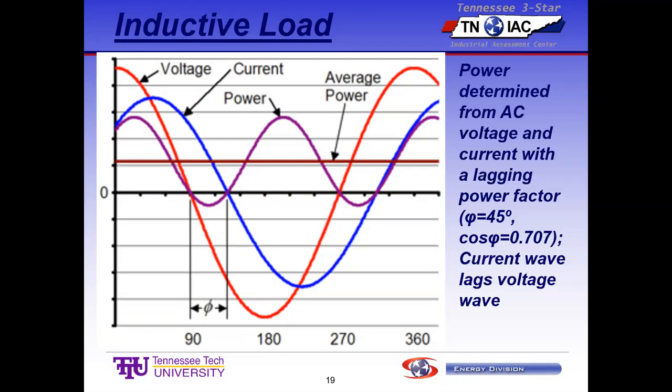But on the leading side, if you go one step past one in the leading direction, they are likely to penalize you. Now, some do, some don't, because the leading power factor really helps the utility. But they can still penalize you for it, and a lot of them do.